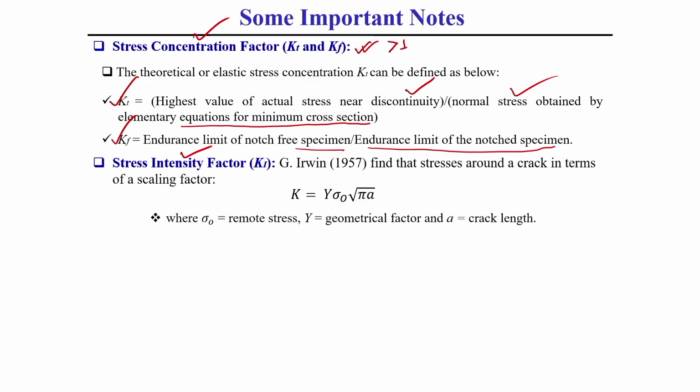I will discuss Paris law in detail and solve some problems on it also. The stress intensity factor was established by G. Irwin, a researcher in 1957, who found the stresses around a crack in terms of a scaling factor. So this stress intensity factor is a scaling factor. This you should keep in mind.